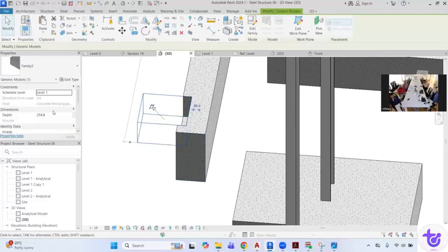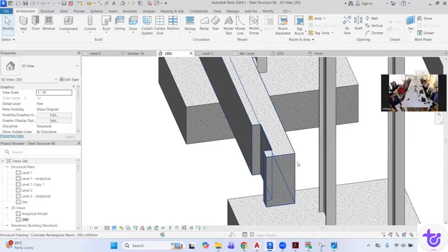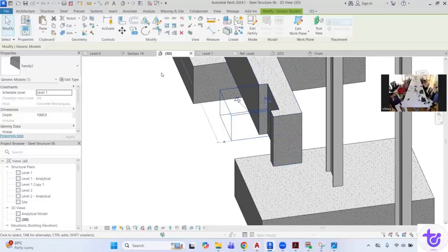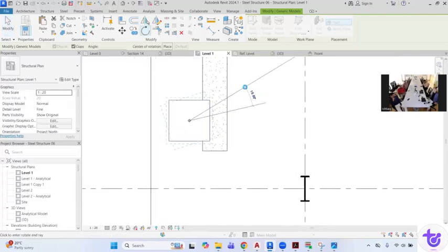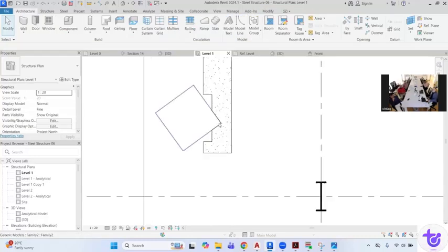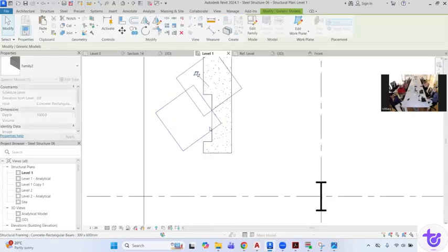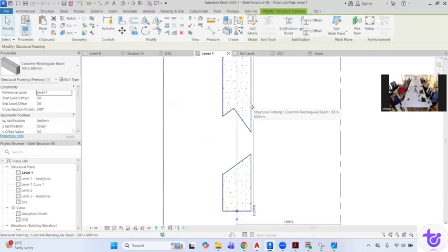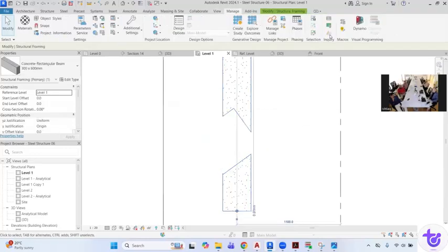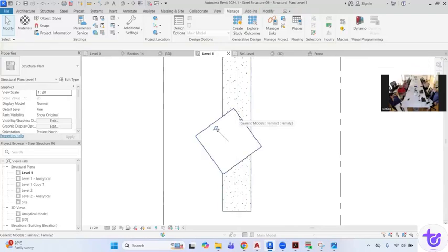And if I put the depth parameter, if I increase this maybe to 1000, it is actually cutting through. And if I want to rotate this, it will rotate the way it should be. Actually, it is rotating by copying. So it is actually cutting and there is no warning. In the manage tab, there is no warning. So you can cut it the way you want to cut.